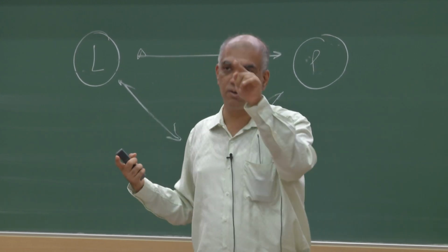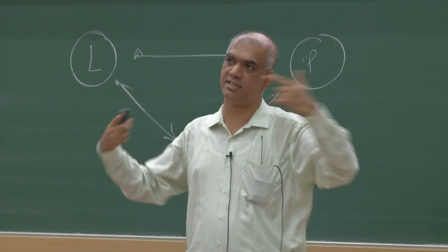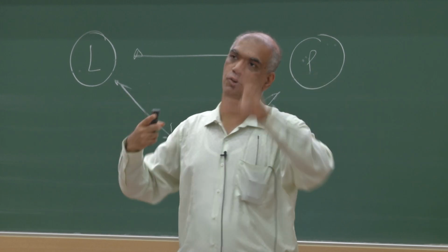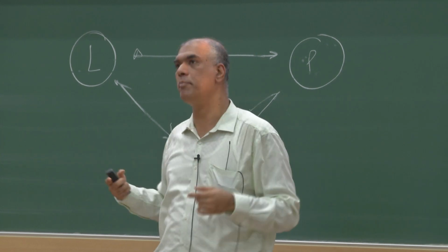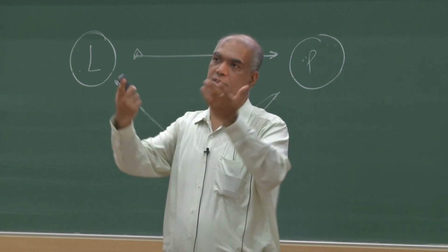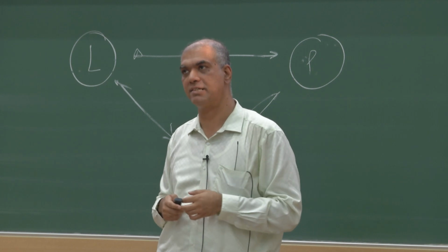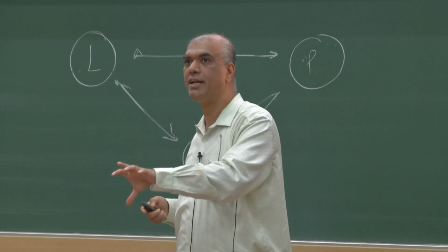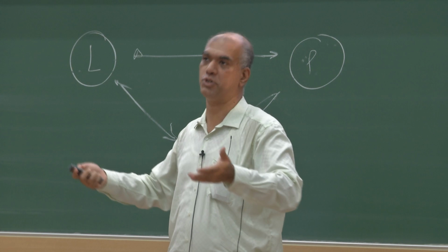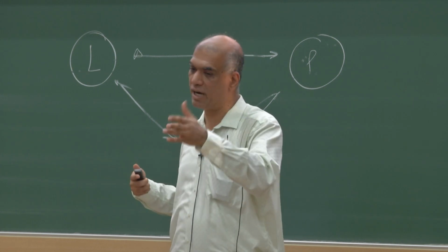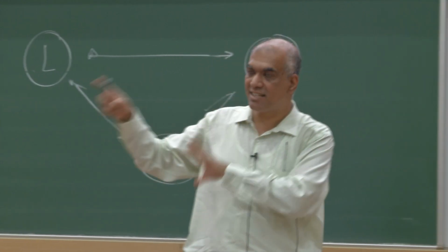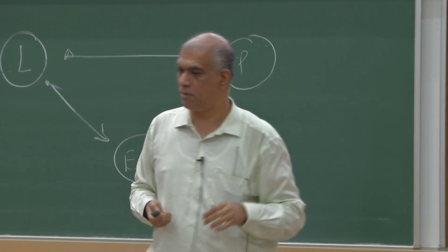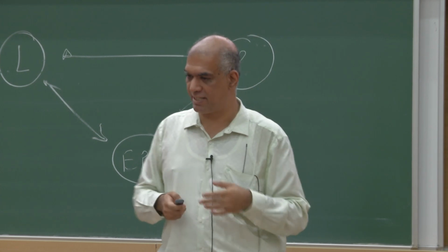You'll often have people ask, what is this symbol, the triangle? And that's just a join, right? In a flow sheet, if you have two streams, you want to combine them, you have a mixer or a join. In a real plant, there's no equipment. If it's two gases or two liquids, they're just going to mix, or maybe you have a static mixer, right? So this is a simulator output, but this is not the way you see a flow sheet. And how is a flow sheet? Look at Kirk-Othmer, look at any chemical processes, look at Professor Madhu's slides. That's a flow sheet, right? So that's what I want to emphasize.